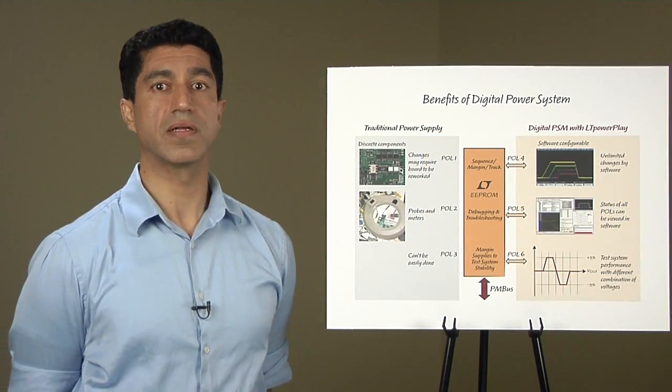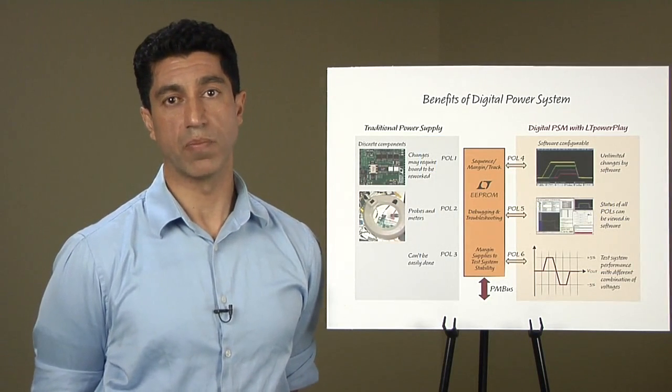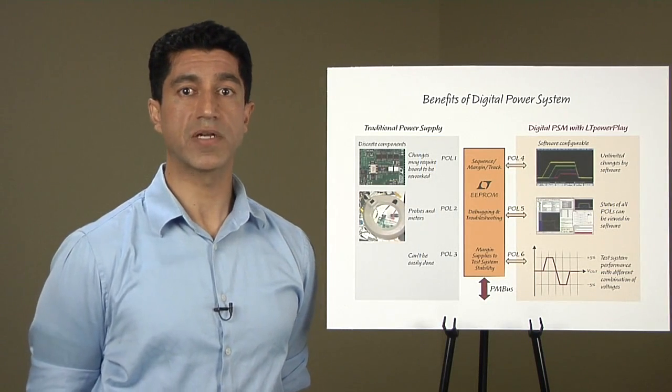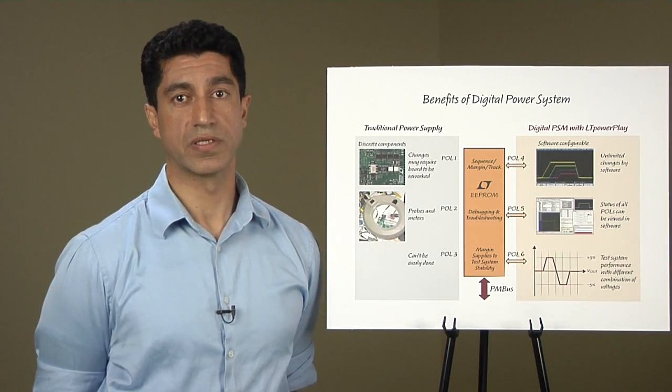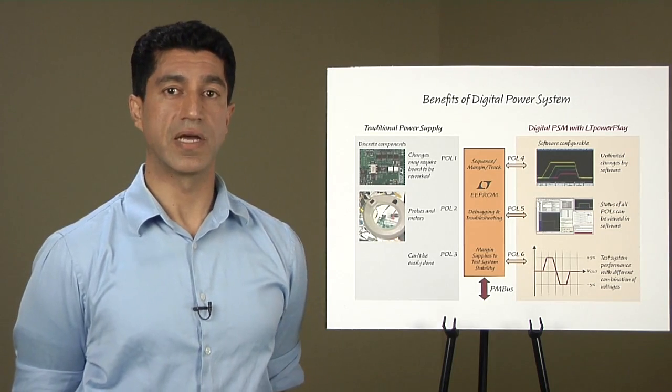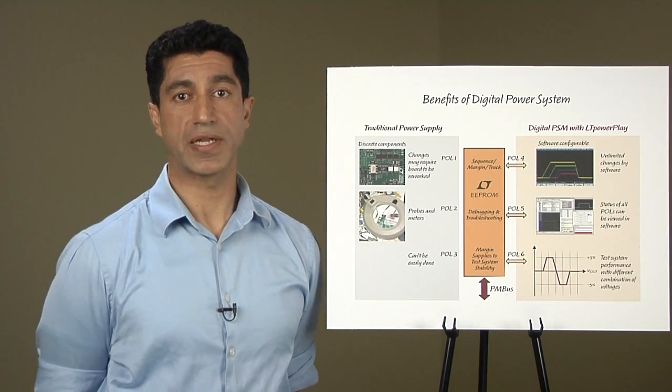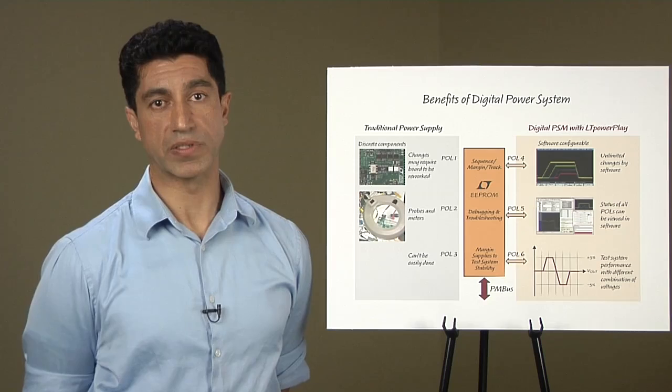Because each POL can have its own margin levels, both high and low, complex patterns of power supply levels can be programmed over the digital interface. This provides a fast and easy way to achieve worst-case analysis of system-level performance.